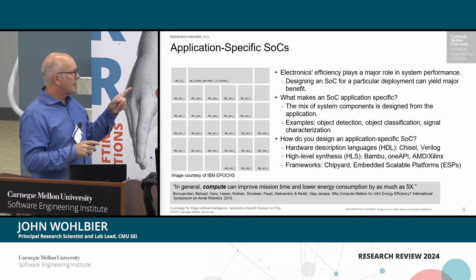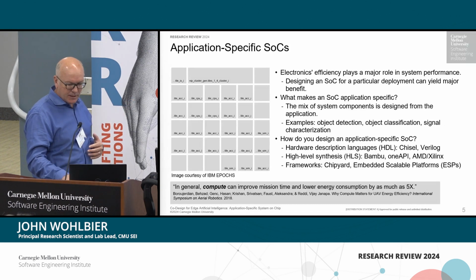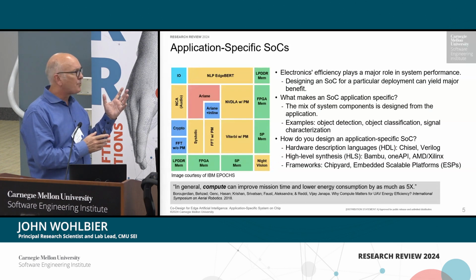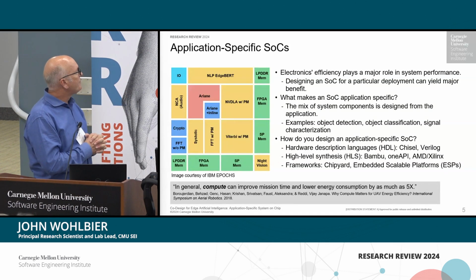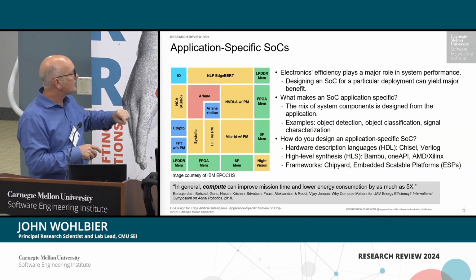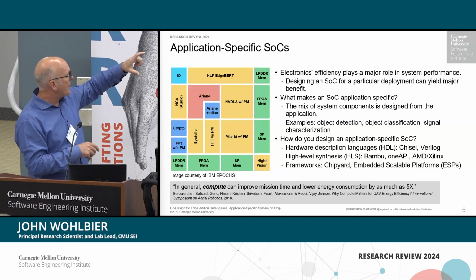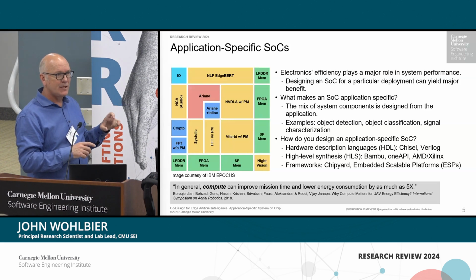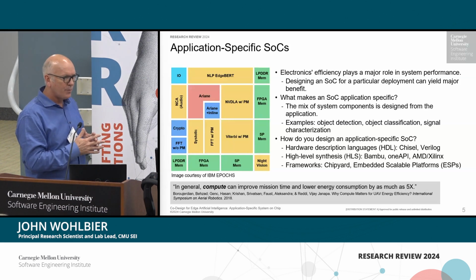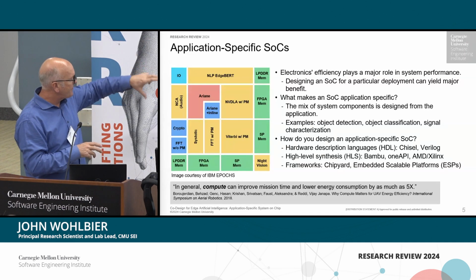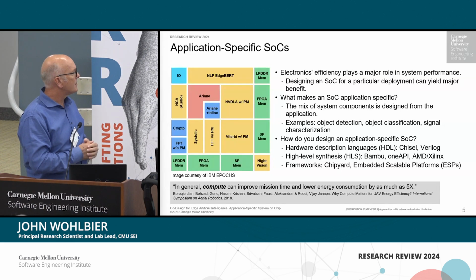And so this is a real example of a real chip that was designed and taped out by IBM during the DSOC program. And this is the specialized IP, intellectual property, that they put in their chip. So you can see you've got an I/O tile, you've got a tile that's for natural language processing. The bigger block, the pinkish block, the Ariane, that's actually 4 RISC-V CPUs. So RISC-V is an open source ISA. It's becoming quite popular these days. Anyway, there's others. There's fast Fourier transforms and all sorts of stuff.